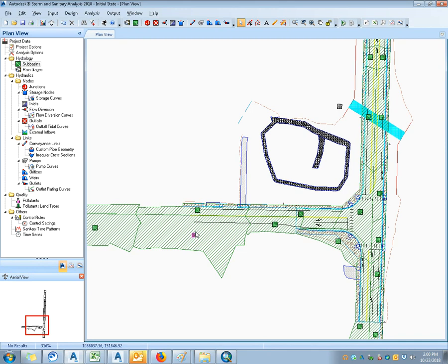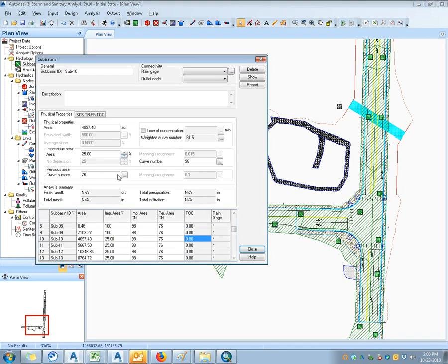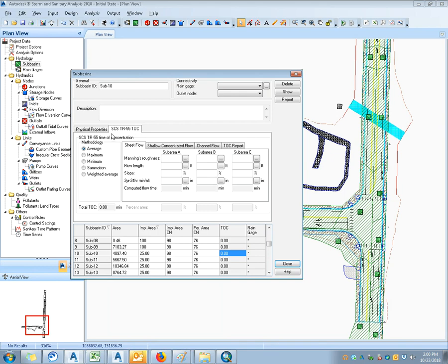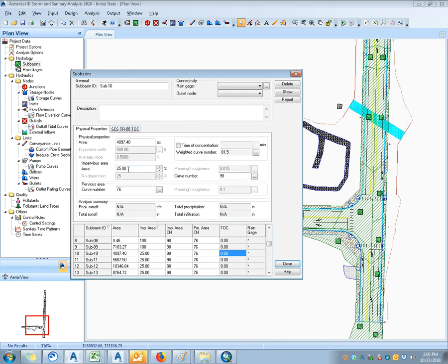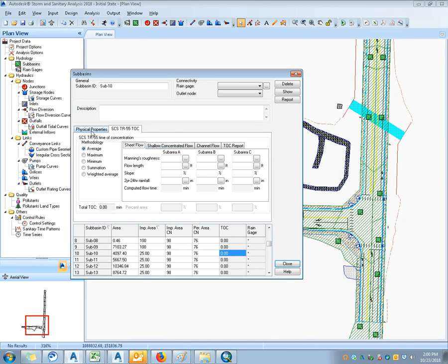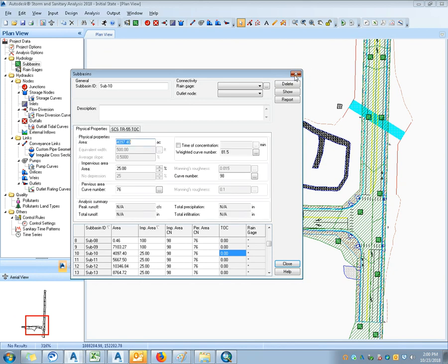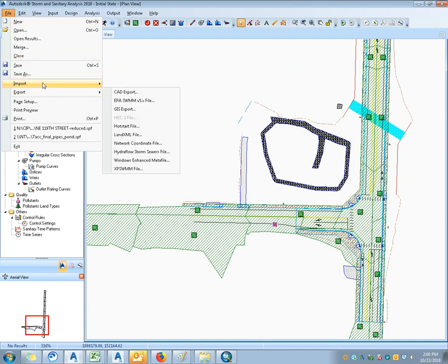Within these land use areas, where you notice the difference is if you have a generalized curve number, or if you have this percent imperviousness, you could play around with that value as well. But that's really just telling you what curve number to use. So at this point, the GIS information isn't good enough to contemplate doing that. We've got to develop it ourselves. It's good enough for planning level, but we're more interested in what's connected impervious, and I don't think it provides a good way to do that.